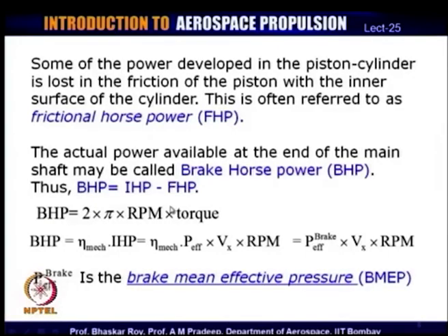We shall see as we go along that the torque produced by the engine is of great importance in running the propeller. The propeller has certain torque characteristics, and we shall discuss that later in this course: unless you meet those torque characteristics, the thrust would not be created. So, the torque created by the engine needs to match that of the propeller, and we know from simple mechanical formulations that the BHP can be written down in terms of torque.